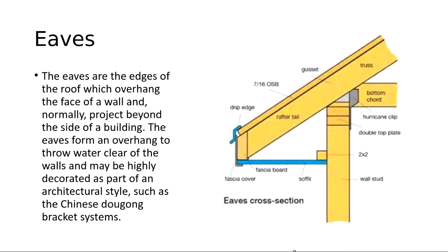So you'll have these long, deeper eaves, and it keeps the water when it rains. It comes down the roof and sheds off over here, away from the building and not at the base of your building. They're also used in a lot of architecture to provide shading. So if you had big eaves on the south side, you would protect your building from the summer sun.